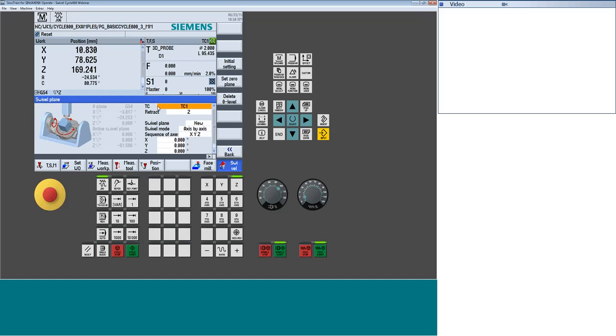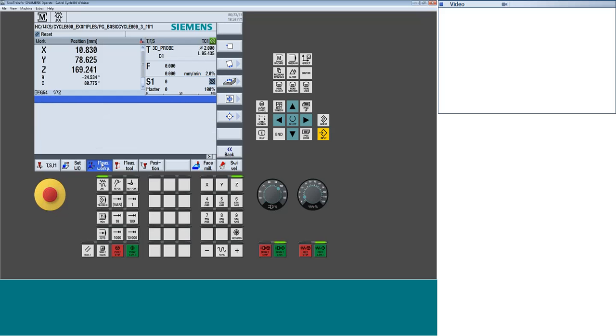So what you do is you use the same measure workpiece. You pick the align edge. There's two features you could use. I could do the base align edge, which will just align the edge, but it won't set a 0. Or you can use the rectangular corner or any corner, and it'll, off 3 points, align the edge and also set a 0 at the corner of those. And then you can change this going around to manipulate it. I would just do a traditional line edge myself and then go back.